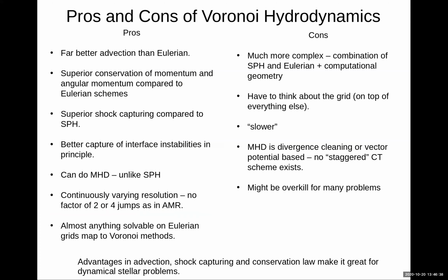You definitely have superior shock capturing compared to SPH. SPH tends to smooth out shocks over several smoothing lengths. In this case, if you use a Riemann solver, you can capture it in basically one cell. You also potentially have better capture of interface instabilities. This is in principle.